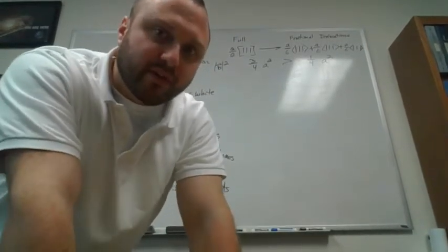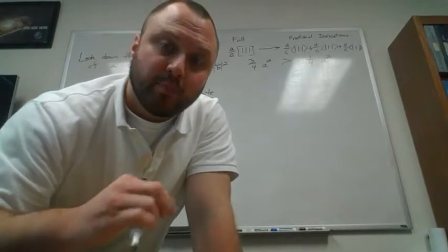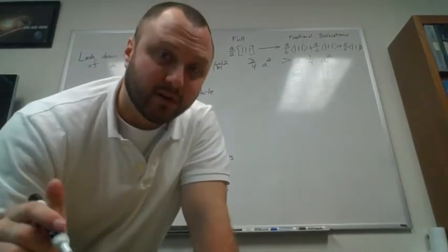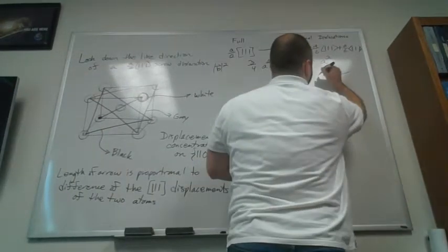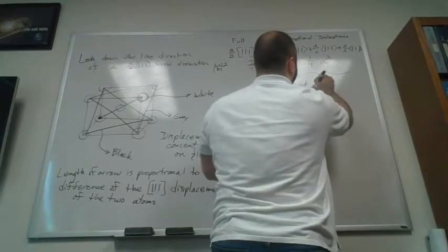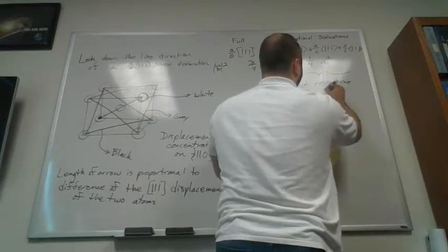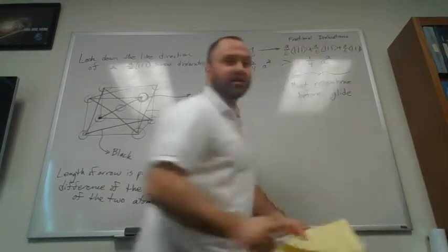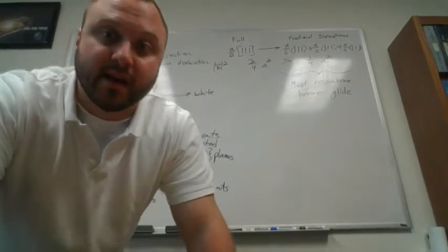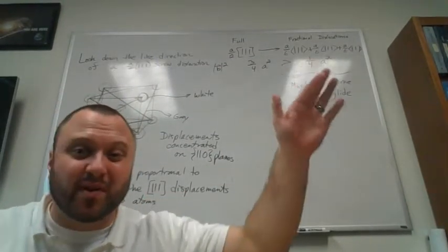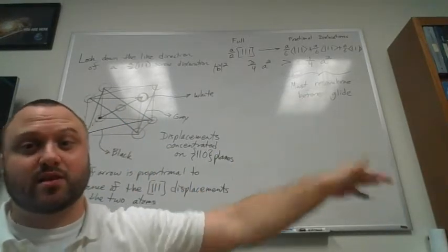And kind of like we saw with our partial dislocations in FCC, where we said that those partials need to come together before we cross-slip, we have something similar, but it's even a bigger deal here. These fractional dislocations must recombine before the dislocation can even glide on its original slip plane. In FCC we were saying the secondary thing, where we move off onto another slip plane, is a little bit harder. Now we're saying even the basic thing, just going along the slip plane that I started on, becomes a lot harder.